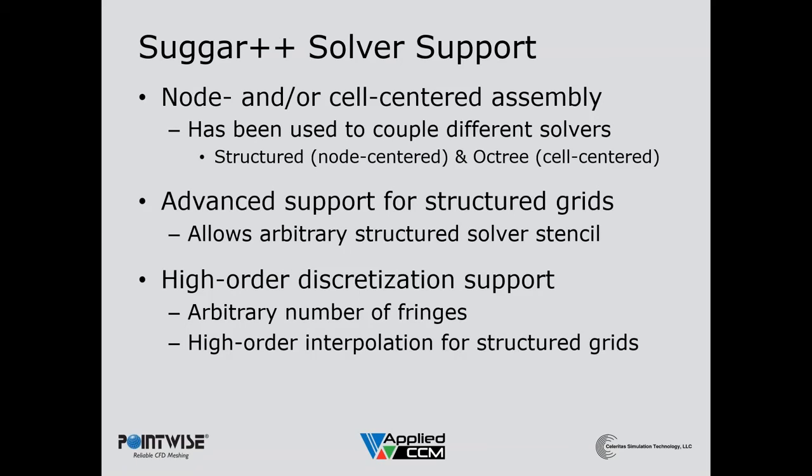It also has advanced support for structured grid solvers by allowing an arbitrary solver stencil. For one run, you can tell Suggar++ that you will only need an inviscid solver stencil, and in a different run, you will need a full viscous stencil, and the fringe requirements will be adjusted appropriately. Suggar++ also has support for higher order solver discretizations. It can provide an arbitrary number of fringes that may be required for your high order flow solver stencil. Arbitrary high-order interpolation is also available for structured grids.